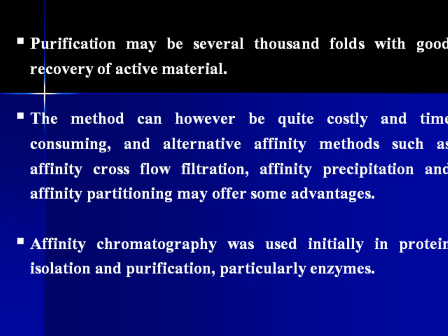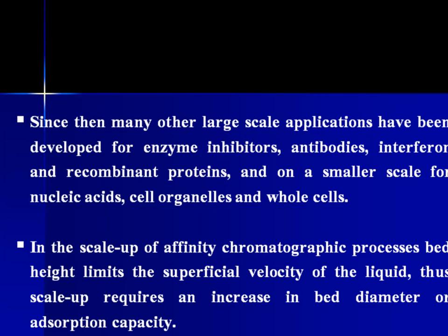Affinity chromatography was used initially in protein isolation and purification, particularly of enzymes. Since then, many other large-scale applications have been developed for enzyme inhibitors, antibodies, interferon, and recombinant proteins, and on a smaller scale for nucleic acids, cell organelles, and whole cells. In the scale-up of the affinity chromatographic process, bed height limits the superficial velocity of the liquid. Thus, scale-up requires an increase in bed diameter or adsorption capacity.